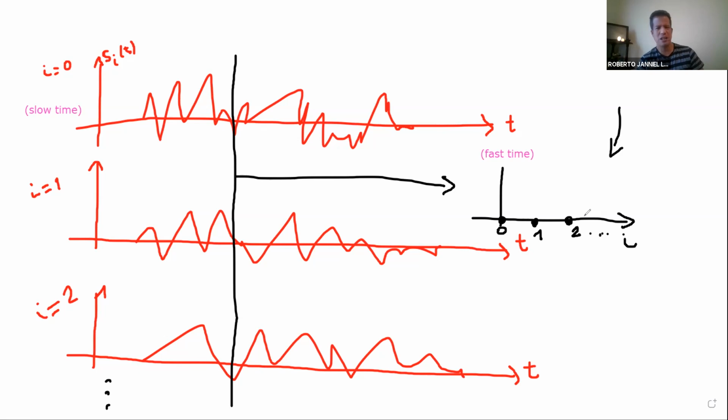Especially nowadays with the electronics we have, everything is discrete time. We have a sample and hold circuit, an A to D card. So you have a voltage and we get sample 1, sample 2, sample 3, probably sampling at 1 gigahertz or something. So we see it changing very nicely. But again, we call it time, which is nonsensical because we actually have samples.